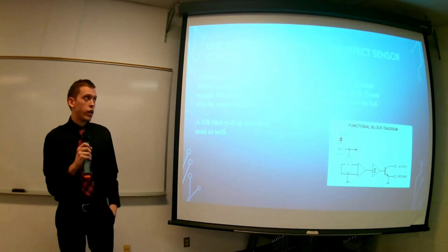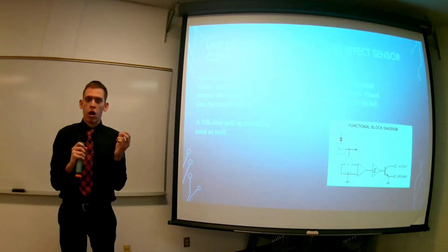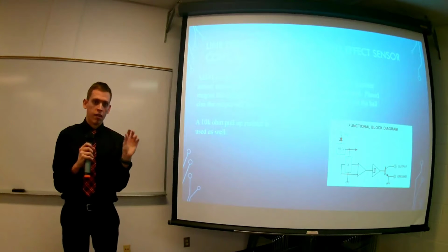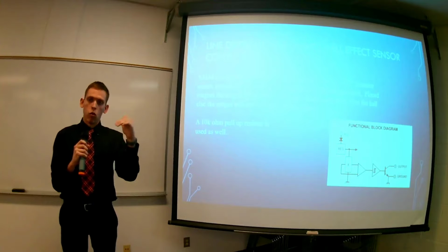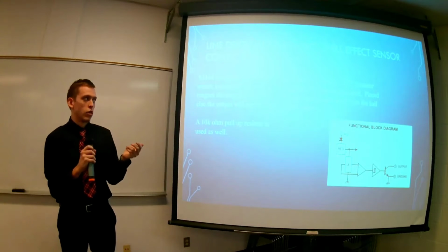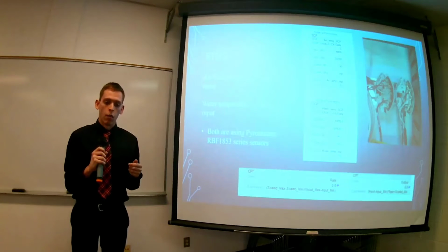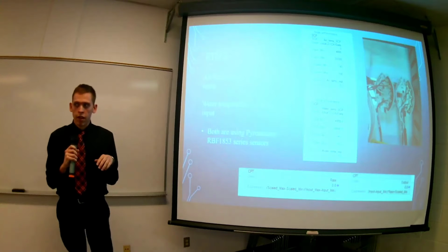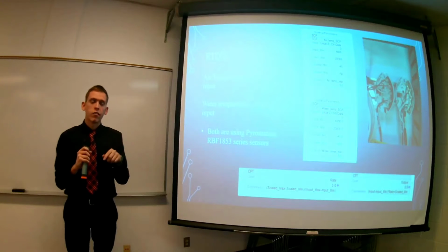So we ended up using 2 sets of neodymium magnets as well, one on each side of the bail. They sit across from each other, and every time they pass the Hall effect, one pulse is done, going low and going high. So that's how we can determine the actual line depth. You'll see later on when David goes over the logic itself, we use normally closed contacts in our ladder logic, and that's the reason why they're normally closed, because of the aspect of that Hall effect sensor.